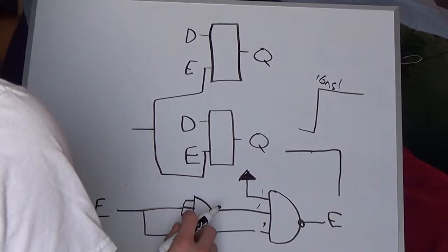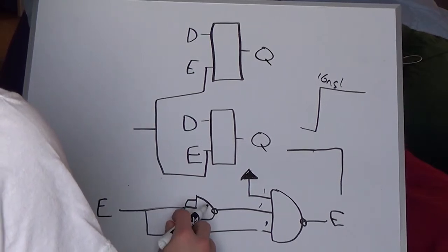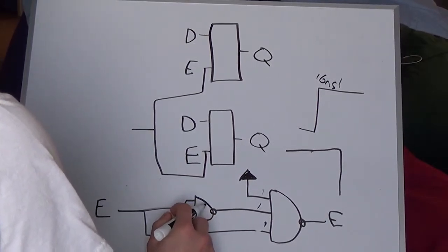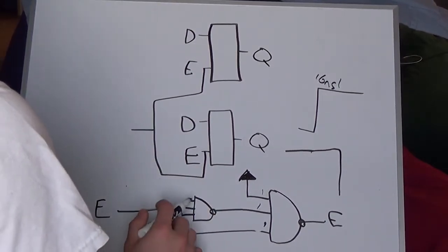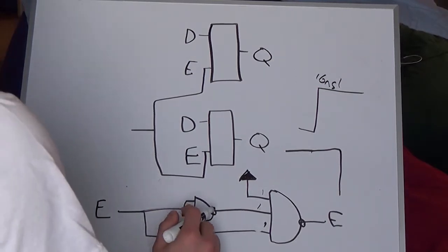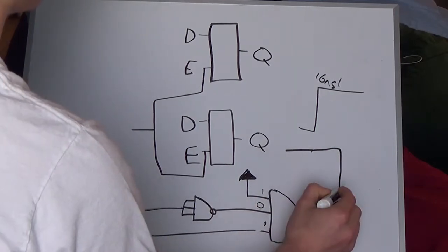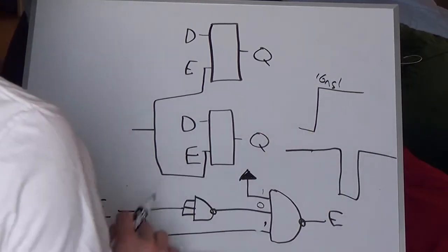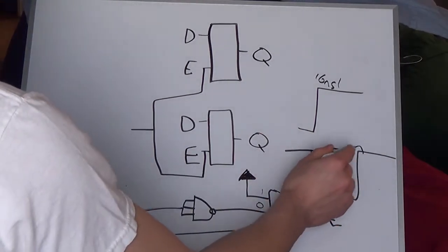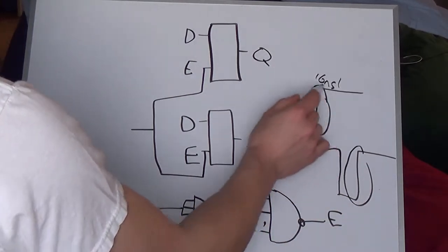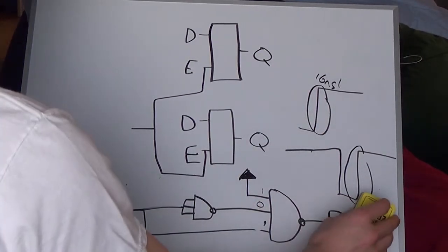And then when this inverter slash 3-input NAND gate does finally switch to low, this signal will jump high again. And so you'll get a delayed signal where the positive edge is after the initial positive edge. And I use that to trigger enable.